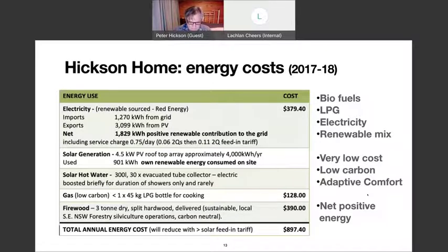During the winter, we use biomass in addition to design and solar space heater to achieve 17 to 20 degrees Celsius in living areas, and we accept 2 to 3 degrees less when sleeping snugly under a doona. Perhaps surrounding radiant heat and stillness allows comfort at a lower winter temperature. Autumn and spring are perfect. In summer, the inside temperatures rarely exceed 24 degrees C and generally sit around 20 to 23 degrees C.